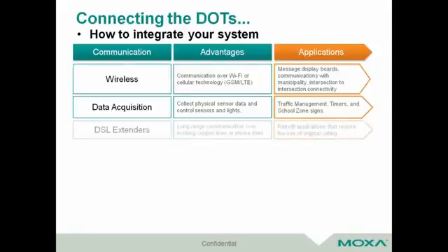DSL extenders. This has been a growing demand, but, let me take a step back, it's a good product to use, but no one's really aware of it. And I would say it should increase in demand shortly because of the retrofit applications. You have long-range communications without having to rip out all your lines. You have DSL extenders that allow you to communicate on both sides, while you still have your Ethernet communications. So essentially, that gives you room to do retrofit applications at a good, decent speed.